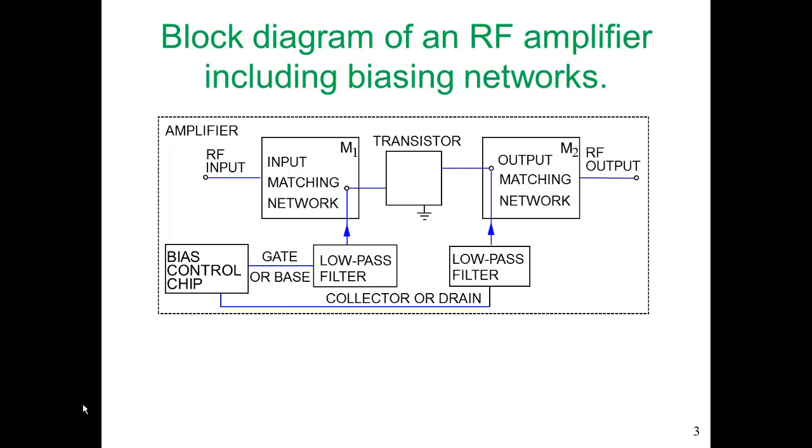So that is what we have today. In the old days, we probably would have used resistor voltage dividers to establish the bias conditions, but that's not required anymore. So that's our basic architecture, and as much as possible, as I said before, we would like to include some of the special bias circuitry in the output matching networks. And so during the design, we're going to have a number of things in mind. We're going to be concerned about stability. We're going to be concerned about trying to incorporate the bias networks into the input matching network.